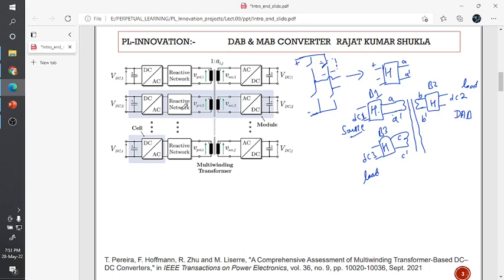Here in this figure is the reactive network. If you are using a simple dual active bridge converter configuration, one inductor term will come with the transformer, which is the power transfer element. This is called the reactive network here. Suppose you add a capacitor, then this becomes a CL converter topology.